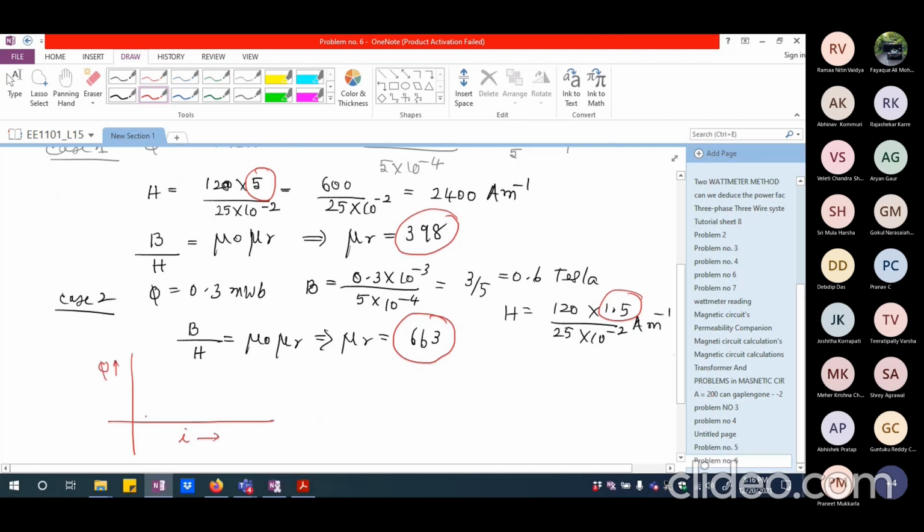So what happens in an iron is, generally if I try to plot what is the current and what is the flux that I am getting corresponding to current, you might see that it is initially going linearly and then it saturates. Normally you will see saturation only in ferromagnetic materials. So the saturation has to be taken into consideration whenever your exciting current happens to be pretty large. The more the current, the more saturation it will manifest. So you will not see a proportionate increase in the flux. So this is flux in Weber and this is going to be current in ampere.